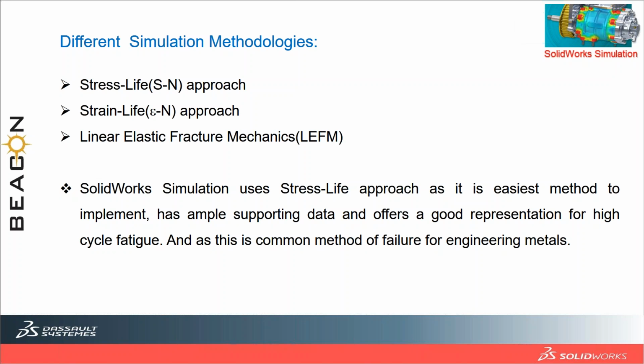So here in SolidWorks, we are referring to the stress life approach, and for this we obtain stress versus number of cycles data, showing how much stress will be induced in that material. When you go on applying the loading, the number of cycles is what matters. This method is easier to implement, has ample supporting data, and gives a good representation for high cycle fatigue.